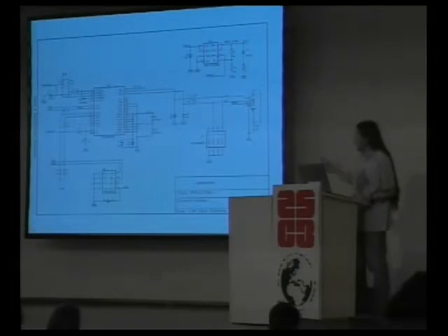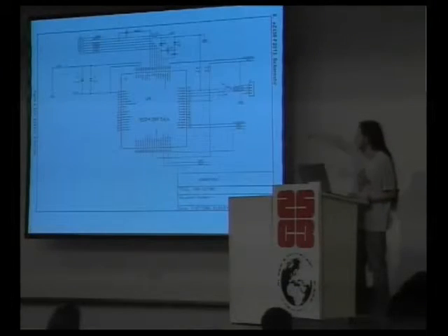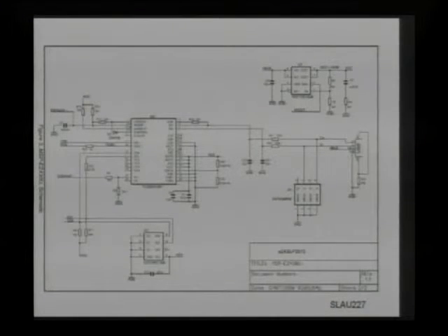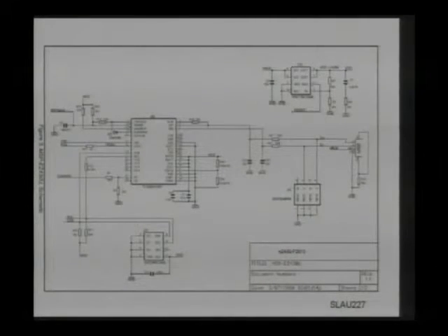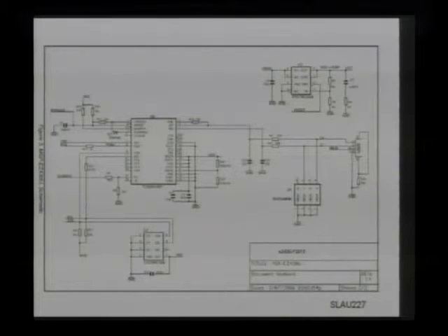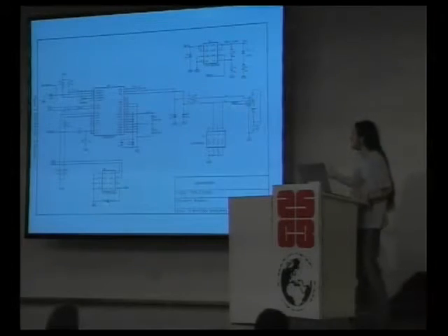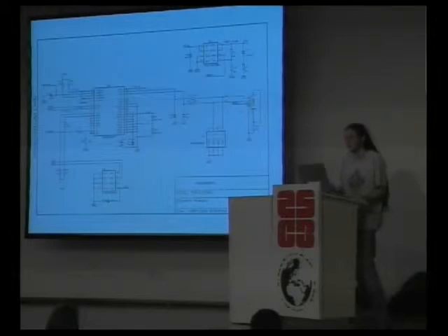But the idea is that firmware for this device resides entirely within the MSP430, which is the CPU of the device, and also within the CAT24 EEPROM, which provides firmware for the TUSB3410, which is a USB to serial chip, and it's also a CPU. It has an embedded 8051 core, and the reason why the red version of this board won't work in Linux is that instead of using the native USB to serial mode of this chip, TI wanted an extra serial port. So they wrote custom 8051 code and then matching software on the PC end to allow them to have 2 serial ports from a chip that in hardware is only supposed to give 1.